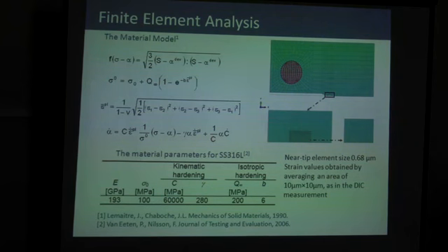So we ran some finite element analysis. Clearly this is a linear elastic problem. We use a quite simple model, but the simple model does include both kinematic and isotropic hardening. And we use the same methods to calculate the strain, the same area to calculate the average strain.